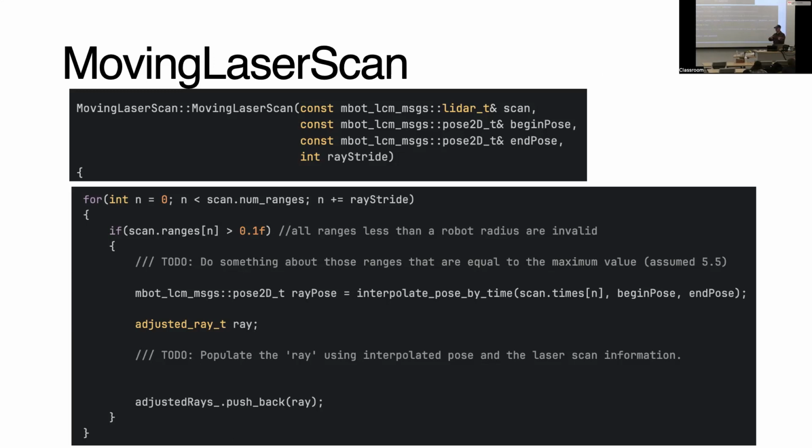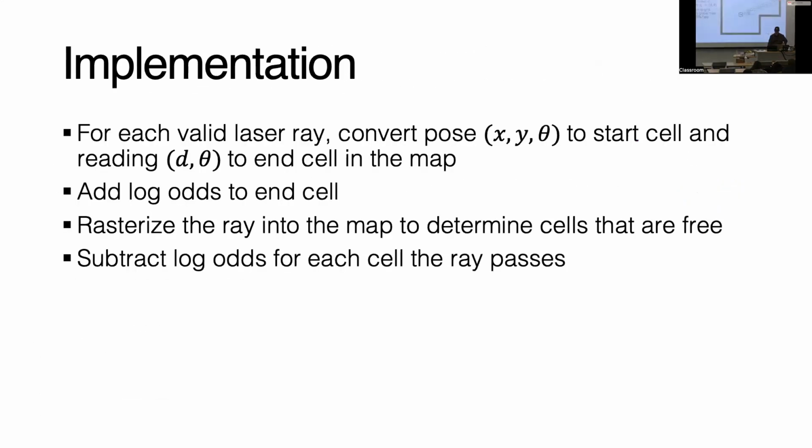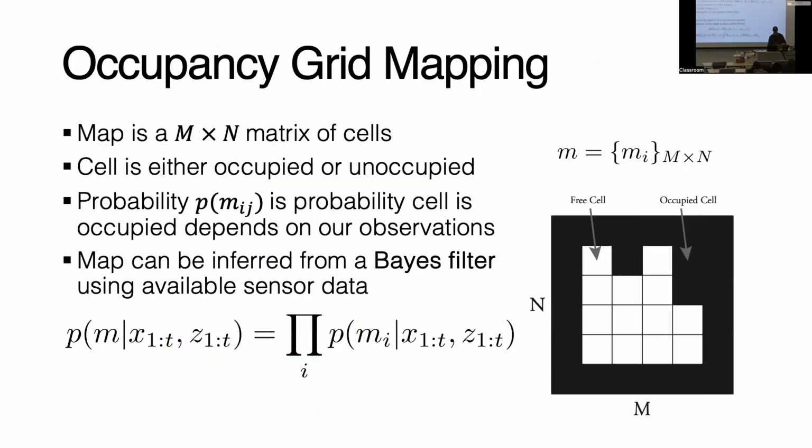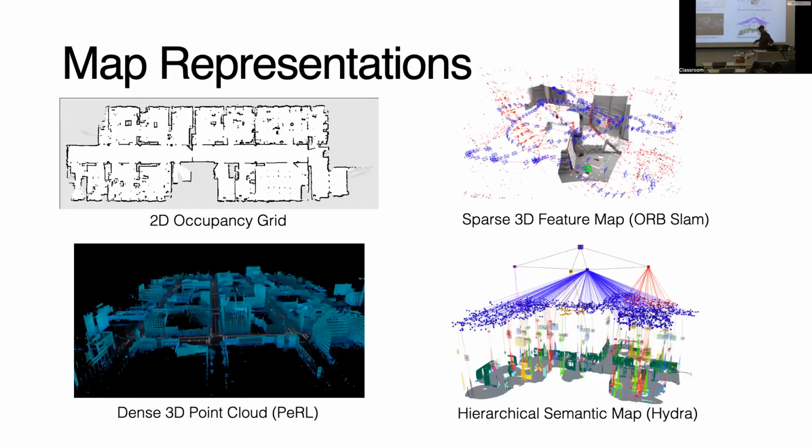You don't necessarily need to turn just to map an area, because as you move around, you're going to see the area with your map. And in fact, a lot of these early robots that are making these maps, their lidars aren't 360 degrees. You can still make this map even if you only see a little bit in front of you, right? Because you can just sort of move around and you're still able to make the map.